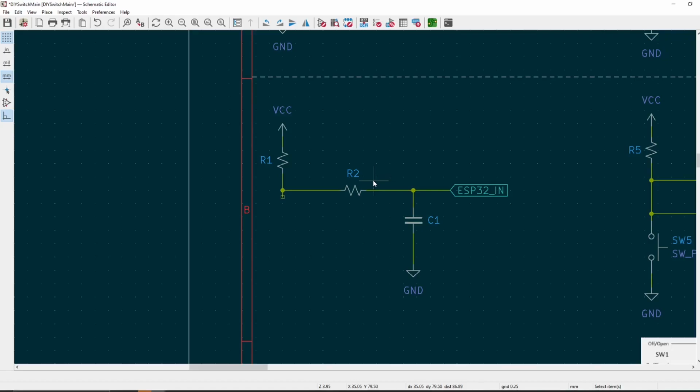So we are now charging with a time constant that is basically equal to R1 plus R2 times C1. So not bad. But we are decreasing the charging time. And when we are discharging C1, now we are discharging only via R2. So this is again not ideal, but we have somehow control over discharging via R2, but again charge and discharge time are not the same, which is what we are searching for.